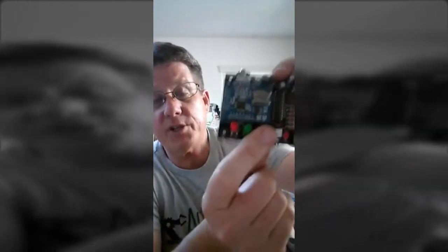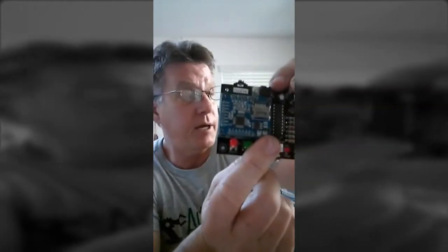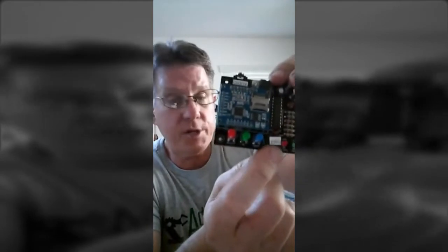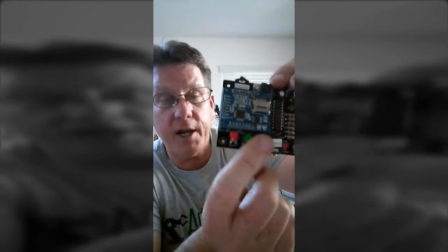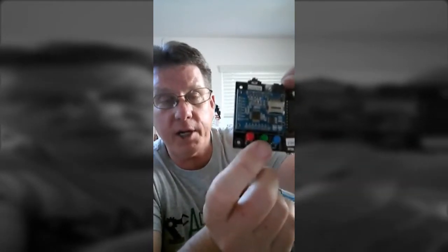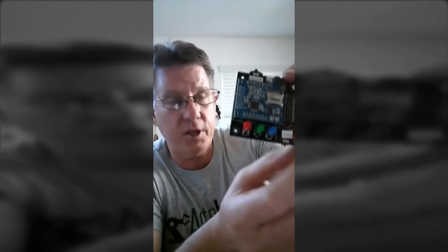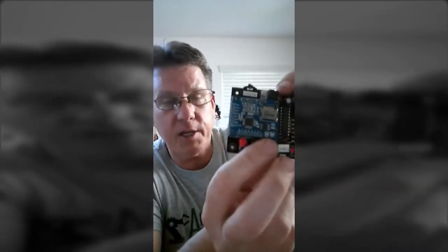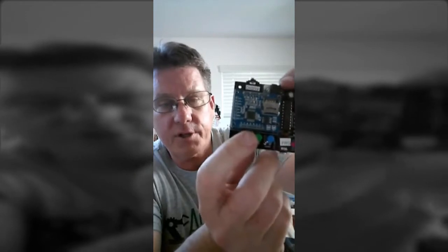So it may say, I want to set servo limits. So it says, all right, open the jaw all the way up, and you use the plus and the minus. You open it all the way up to where you want it as a limit, and you set. Then it may say, all right, set the closed position, and you do the same thing. You move it up, get it closed, set. That's it. That's all you're doing. So it's really easy to set up the limits. 3 minutes, 5 minutes max.